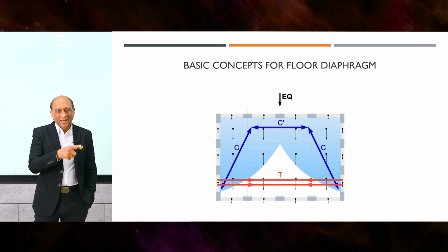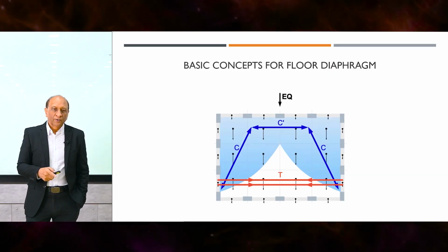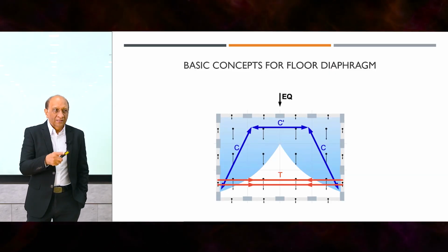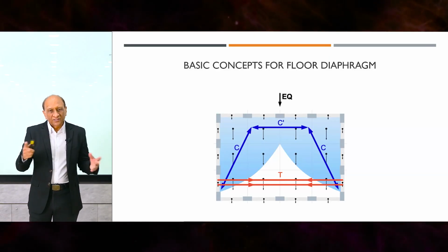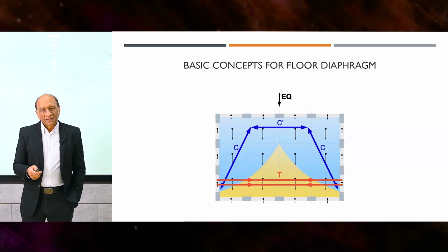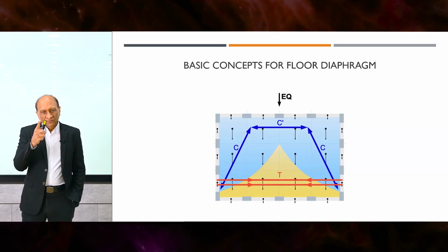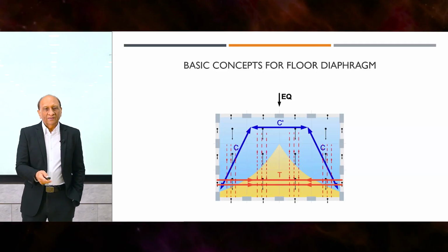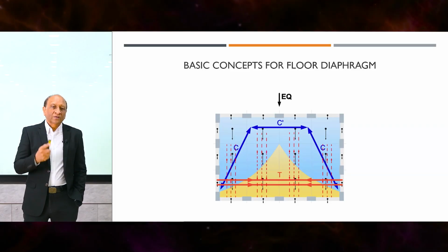And then you can have a compression system forming and a tie forming at the bottom. So this becomes the internal force transfer mechanism within the diaphragm, a large diaphragm with compression and tension. And then that portion will be in tension. So to prevent this portion from splitting down, we can tie it back, sometimes called the collectors, and tie it back to the compression.